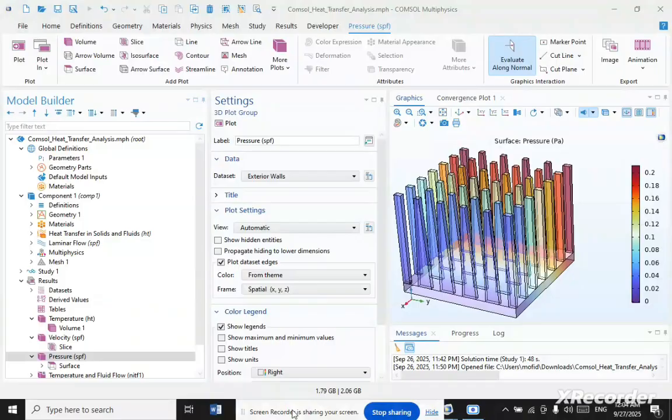The second one is that the optimal range of porosity for micropin fins is 0.5 to 0.6 for enhanced performance. The third one is the staggered arrangement has consistently shown better thermal performance than the inline arrangement, but at the expense of pressure drop. The fourth one is for augmented performance, the sidewall gap to pin-fin diameter ratio should be kept between 0.8 to 1.1. The fifth one is the tip clearance in the heatsink should be a manageable size. The optimal range for the tip clearance is 15 to 20% of the channel height.